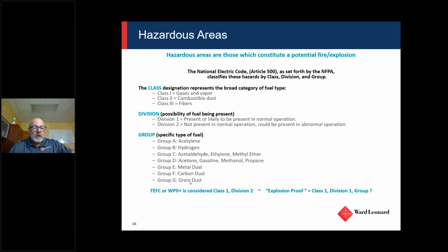So if you were at a grain silo, you would probably be using Class 3, Div 1, Group G, right? What that really is about is if the motor fails, if there's an electrical failure, typically when motors fail, there could be an electrical arc that gets out of the motor.